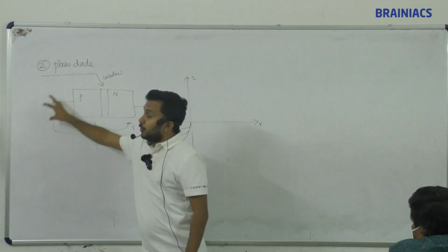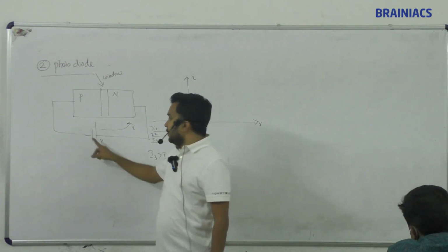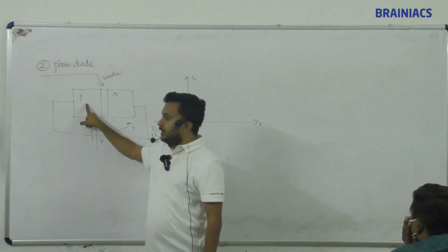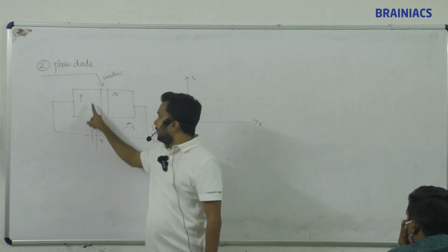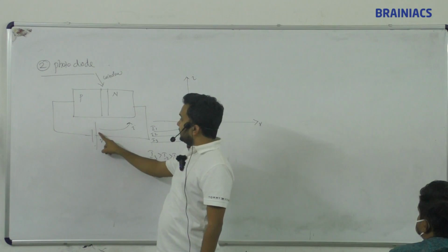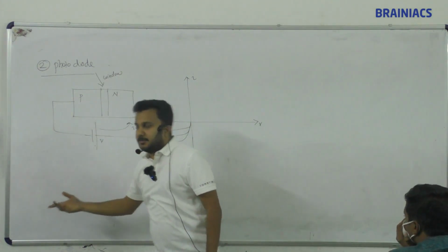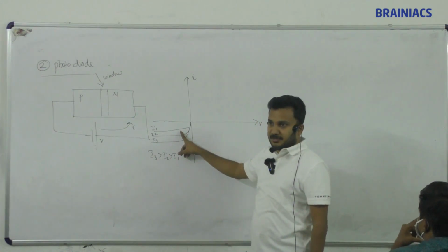and all the electrons are trying to move to this side. But this is the majority carrier movement; as well as that, there are minority carriers. Electrons are repelled by the battery and move inside. Holes are repelled by the positive and move towards this side. So there is a minority current. That is the representation of minority current.